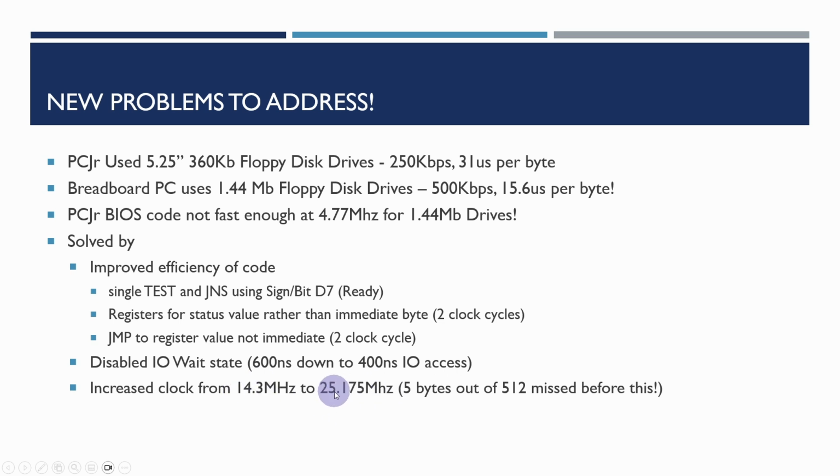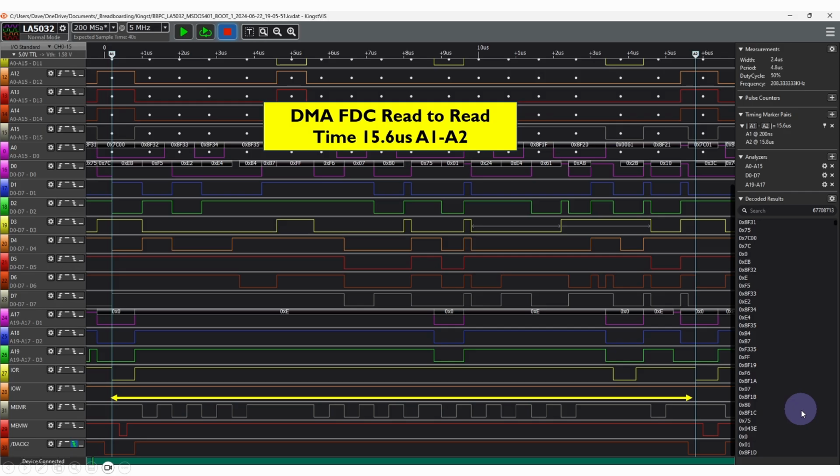Now what we're doing in this one is, because we're using an Intersil processor which is capable of working up to 8 MHz, we're going to use the VGA dot clock frequency divided by 3, and that will give us about 8.3 MHz, which should mean that we won't miss any of the data. When running at the standard frequency, we'd miss about 5 bytes out of every 500, which obviously would cause a problem.